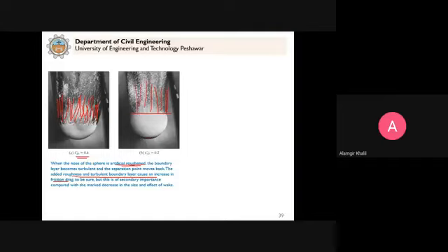It is written that although we are making the surface rough, and the aided roughness and turbulent boundary layer cause an increase in friction drag, this becomes of secondary importance if we compare the marked decrease in the size of the wake. You can see here the effect and size of the wake, it has shifted from here to here.